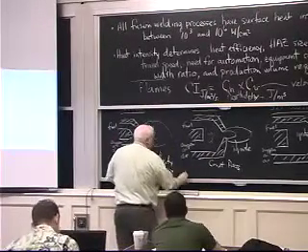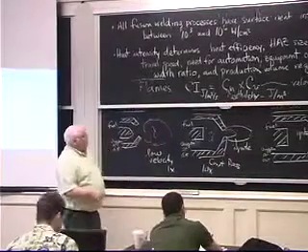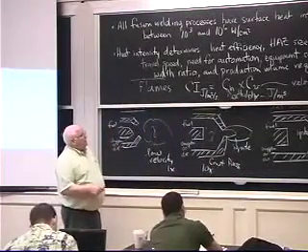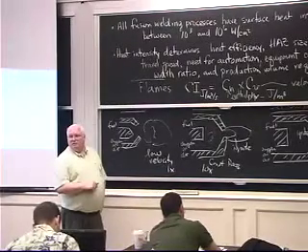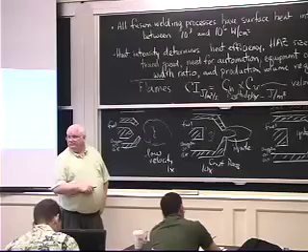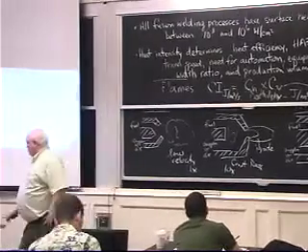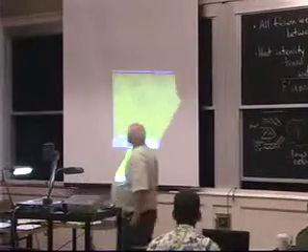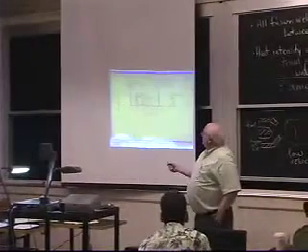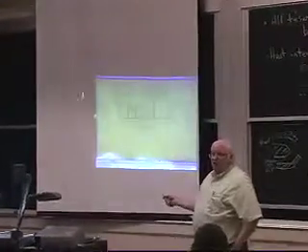if this is 1x, this is probably 10x or more. And so it turns out the premixed flame has a combustion intensity probably 10 times greater than the diffuse flame, maybe 100 times greater, depending on the fuel and everything. Well, I told you, if I put this back up, that a candle was 1 to 10 watts per square centimeter, and this air fuel gas flame, like the red propane torch there, is 100 watts per square centimeter, where there's my factor of 100.